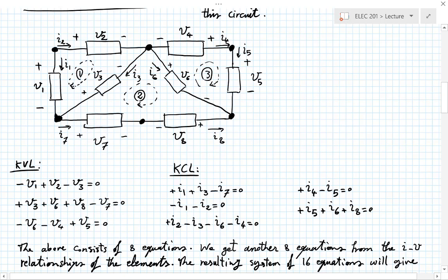It just happens to be that I got there last. So I had already written 5 equations. But I could have written equations for all the nodes but the top right one, and then the top right one would be dependent. It would not be a separate equation. So you don't have to worry about which one. Same for the loops. You don't have to worry about which loops will give you dependent versus independent.